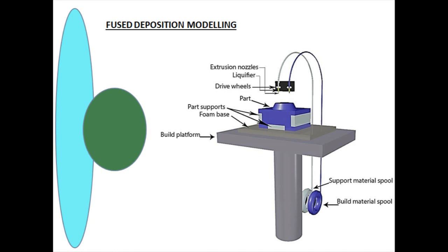During printing, these materials take the form of plastic threads or filaments which are unwound from a coil and fed through an extrusion nozzle. The nozzle melts the filaments and extrudes them onto a base, sometimes called a build platform or table. Both the nozzle and the base are controlled by a computer that translates the dimensions of an object into X, Y, and Z coordinates of the nozzle and the base to follow during printing.